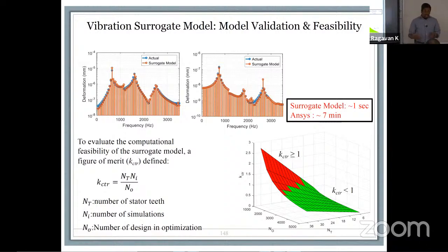Once again, it's a large number when you're talking about it, but the idea here is that it allows you complete design flexibility in the entire design geometry. So we define multiple frequencies, multiple shapes, or multiple components of the stator that we wanted to optimize it for. You see here, the actual and surrogate model have a very good fit.